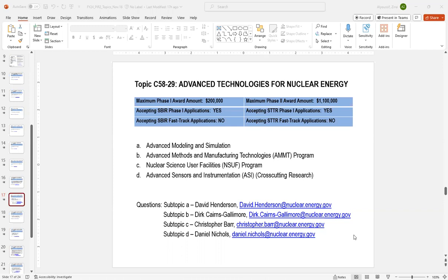The flux in the in-core region may be between 1e13 and 1e15 neutrons per centimeter squared per second. So then taking into account the survivability duration of that sensor, that is the sort of fluence, integrating over that time, that they would have to consider as part of their design if they're deploying in the in-core. And then of course, there's near core applications, and then there's near vessel applications. So moving further away from that most adverse condition. And then there's just in containment, and then there's beyond containment conditions.